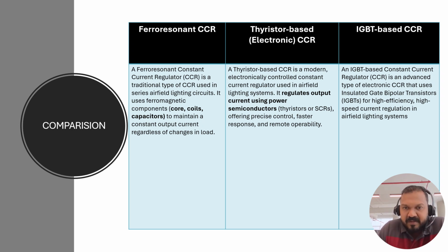Similarly, the thyristor based electronic CCR regulates the output current using power semiconductors, especially the thyristor, which is an SCR, silicon controlled rectifier. In the next section we see the IGBT based CCR, which also controls the output current through semiconductors. Basically, the thyristor and the IGBT transistor both come under semiconductors.